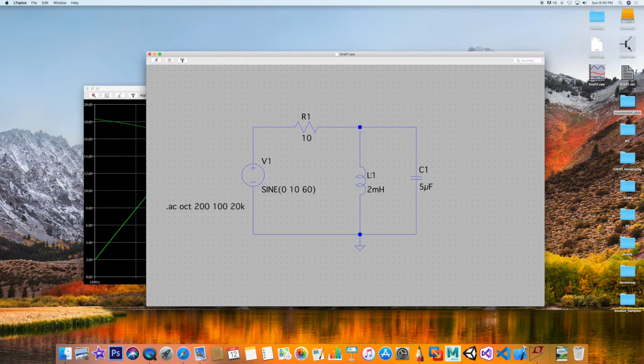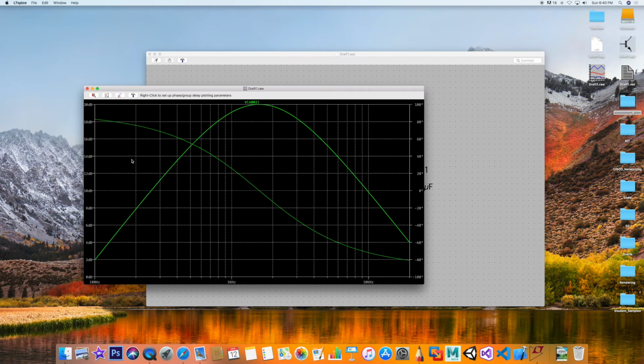right? They both, each one, remember they're 180 degrees from each other. They cancel each other out. And I'm left with 10 ohm as being my resistive circuit for the whole, as far as the impedance is concerned. However, I want you to observe what happens if I lower or increase this value. Now, that's going to be important in case you want to create a tuner of some form, right? Let's lower the resistance and see what happens, which means now what's going to happen is most likely this curve will flatten, okay, a little bit.